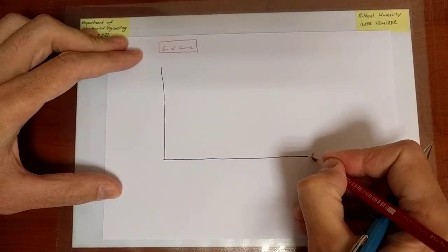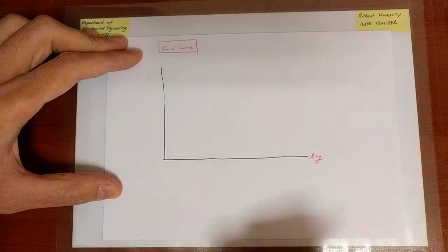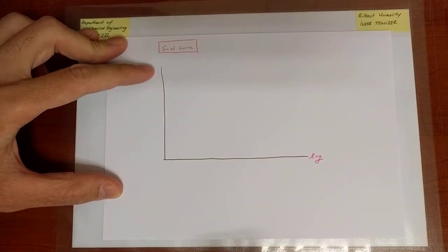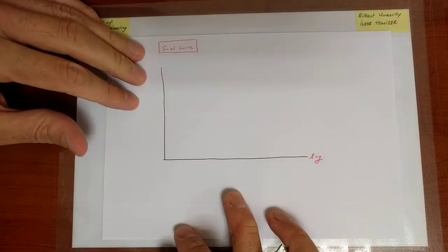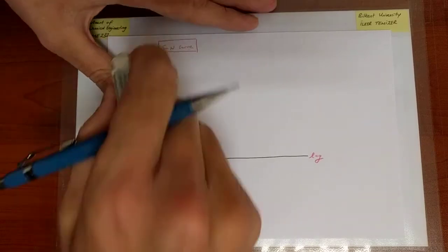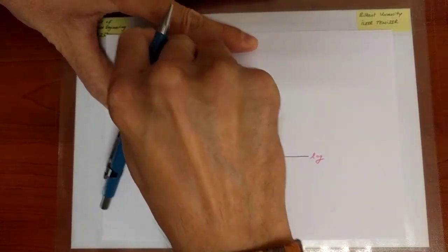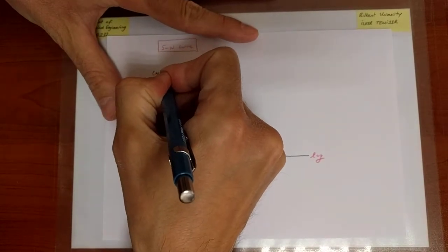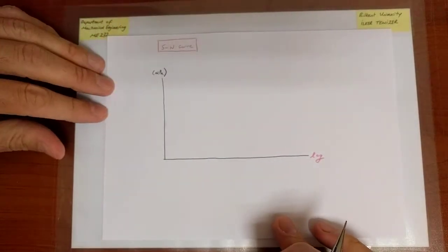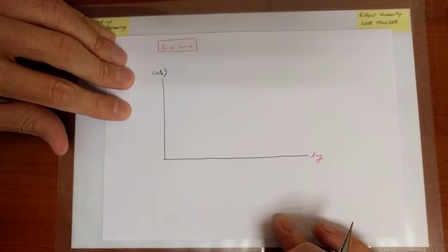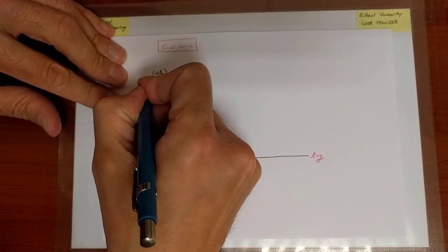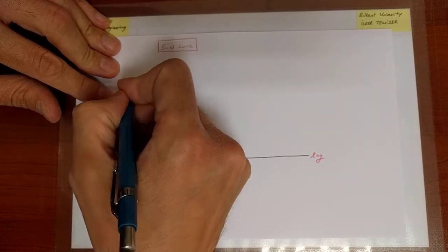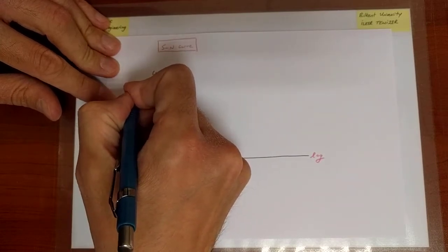So what is important is that that axis is always log scale. The vertical axis is not necessarily always linear. Sometimes it is log, but in most cases it is of linear form, so it's non-log. And I'm just going to write the dimensions here, usually just MPa. So it's non-log or linear scale, and that is the alternating stress or the stress amplitude, which is, remember, going